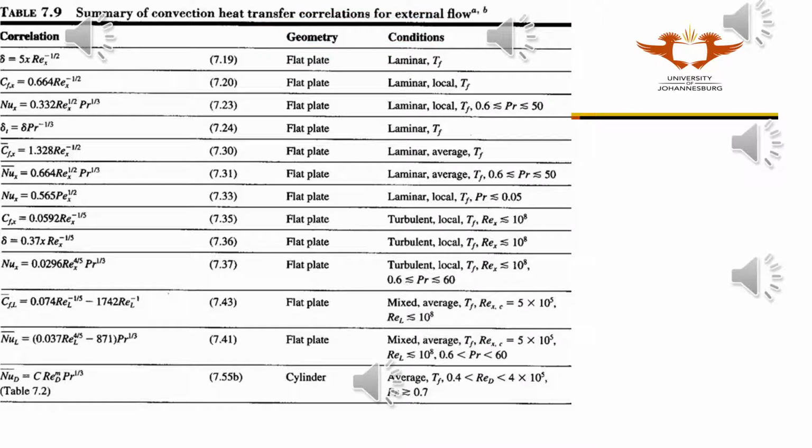You should choose a Nusselt number correlation, as you can use this to calculate the heat transfer coefficient, which is equal to the Nusselt number, divided by the characteristic length, times the thermal conductivity of the fluid. You usually need to use the average Nusselt number, to give the average heat transfer coefficient. Multiplying the average coefficient, by the total heat transfer area of the plate, and the temperature difference, will give you the total heat transfer rate from the plate, Q.